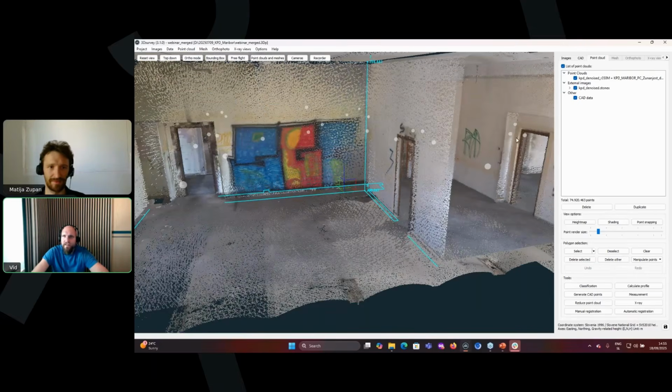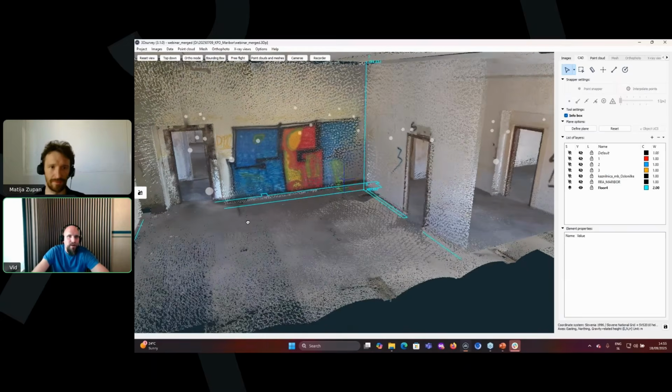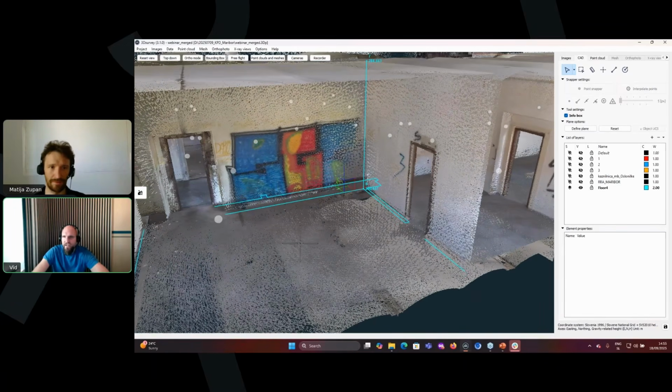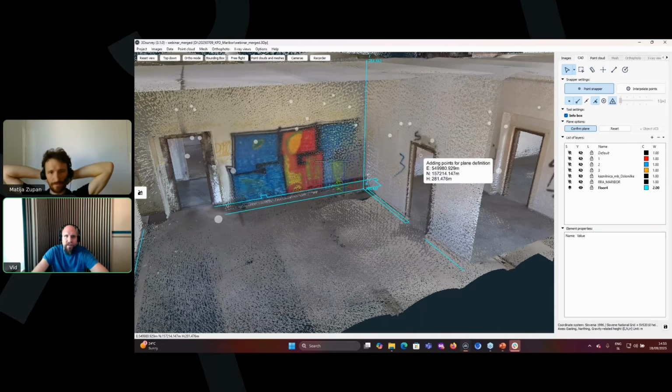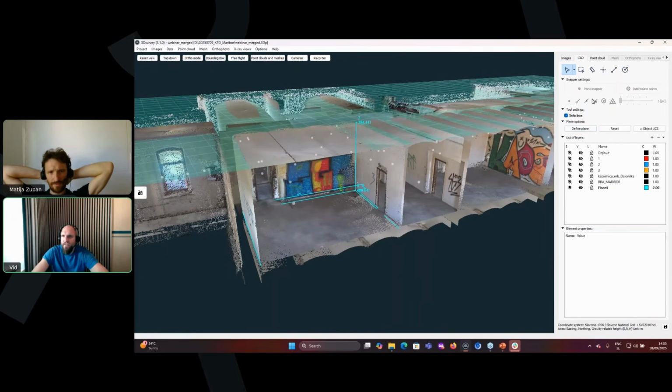Now let's say that I go back here into CAD and I will repeat that. First we draw the line along this. Now I want to create a vertical plane. First thing I will do, I'll go here into CAD. I could use this point up here, but I will just draw it again. First, define a plane and create a vertical plane. Confirm it.